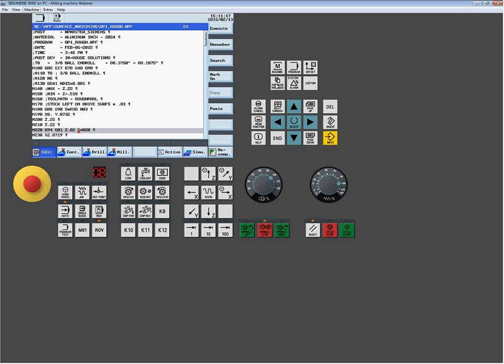Now, a couple of the other modifications I did in turning this into a subprogram: I commented out, certainly not deleted, all tool change commands because I want to do that up in the main. I don't want to have nested tool changes. I commented out any kind of advanced technology cycles, corner rounding, forward functionality, anything like that. I don't want it here. I want pure cutter path.